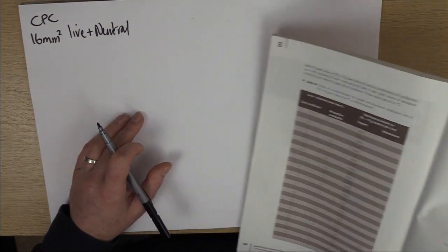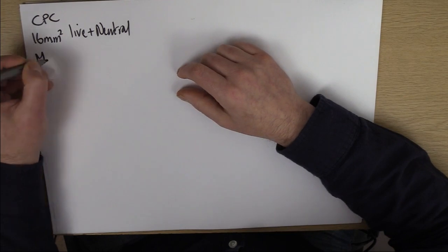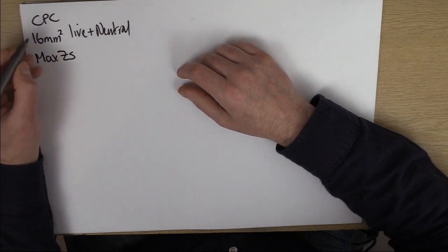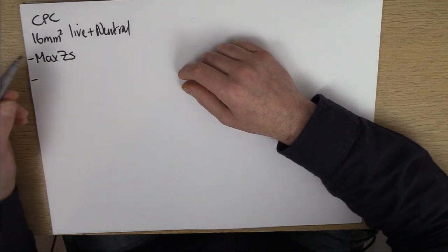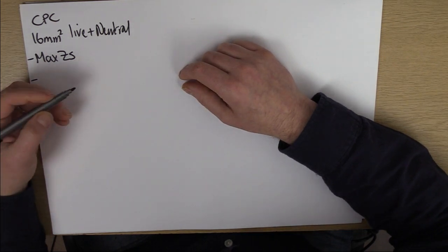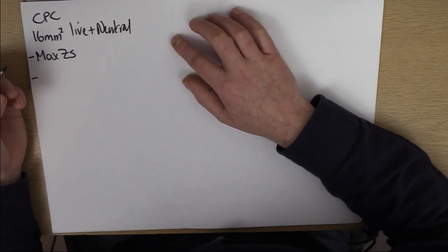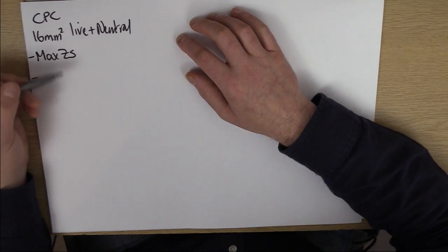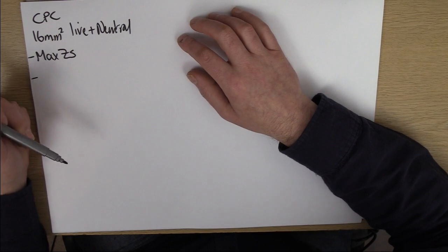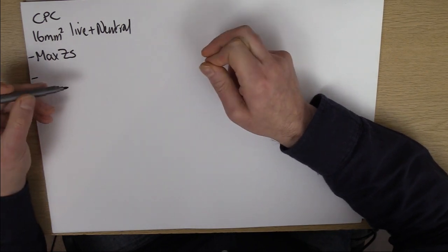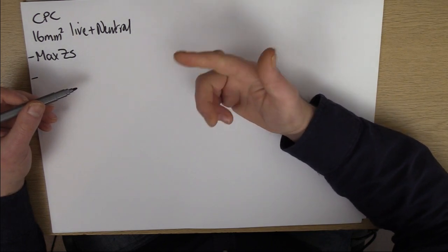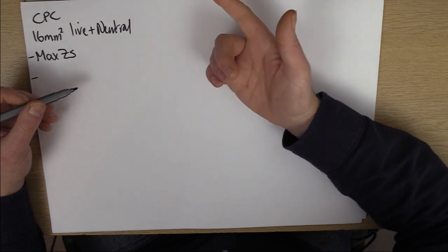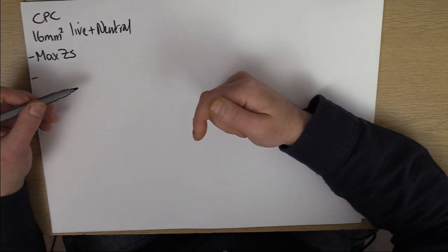Yes. So what are we checking for with CPC? We need to make sure that it complies in terms of its earth fault loop. So we need to know our max ZS, our target, if you like. And we need to make sure it complies with thermal constraints. So during the fault, is the CPC going to destroy itself before it disconnects? That's what we're after. So again, there's two methods. We can either just take a stab in the dark and check it for compliance, or we can rearrange and find out our maximum R1, R2, which in turn tells us our maximum milliohm per meter value, and then we can choose a cable fairly quickly that way.